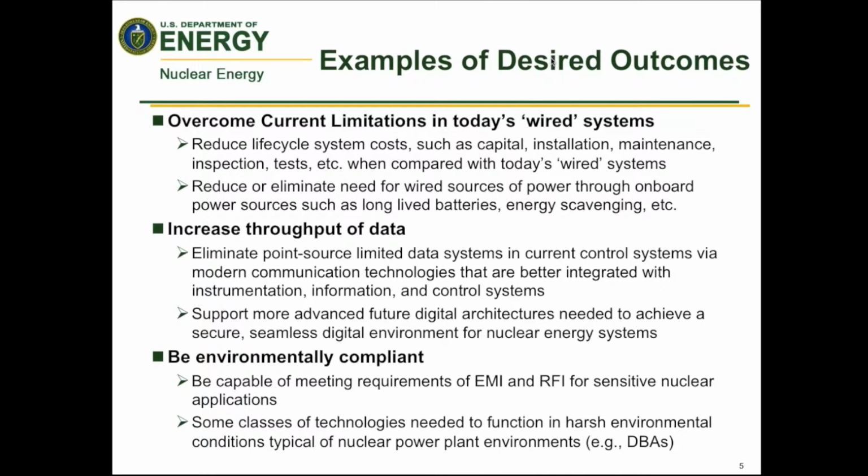Need to understand the environment where the technology will be applied. Be capable of meeting the requirements of electromagnetic interference and/or radio frequency interference for sensitive nuclear applications to make sure that they don't interfere with the nuclear plant operations. And understand the harsh environment conditions typical of a nuclear plant environment. I mentioned that before. If it's going to be after an accident, you need to understand beyond design basis requirements.